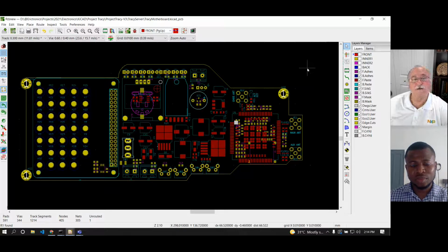It reduces the amount of chemical that's consumed during the creation of this board, so it makes it greener. And then when you go to manufacturing, the board profile through the reflow oven is going to be more uniform, and you'll get better yields in your assembly process. And then because we've followed these rules, it will also be more robust from an ESD perspective. So it will be able to survive more abuse at the hands of a customer or user than it would be without following these rules.